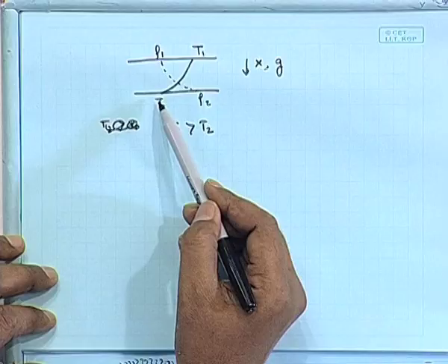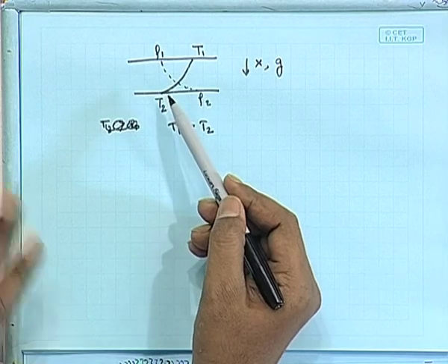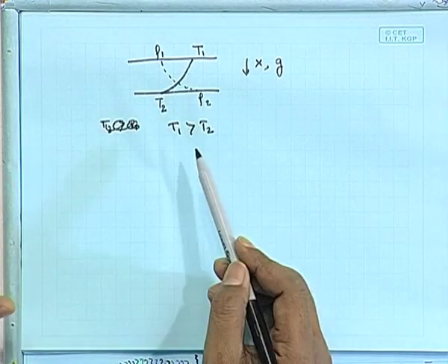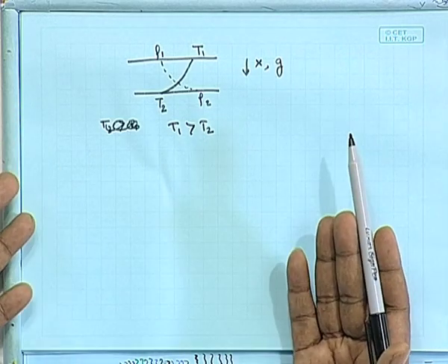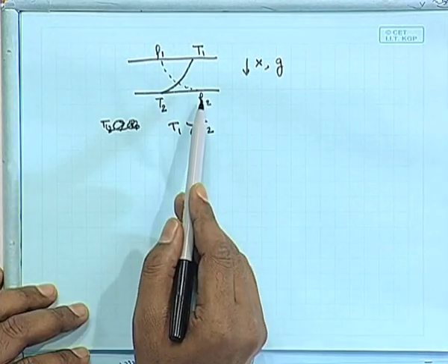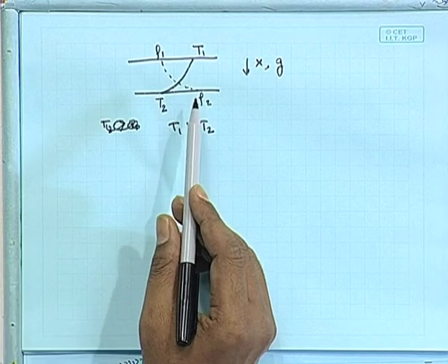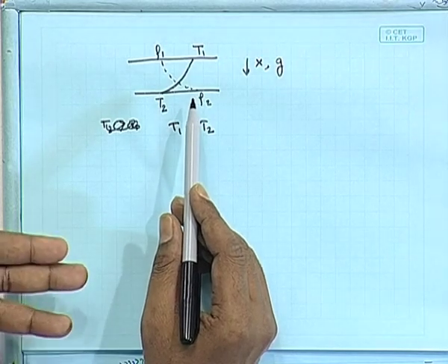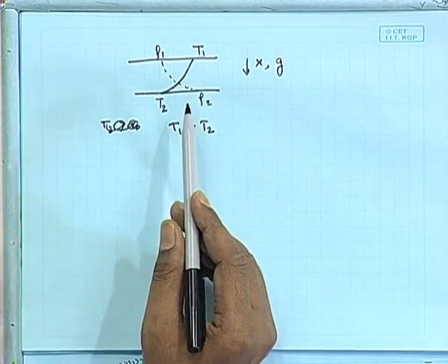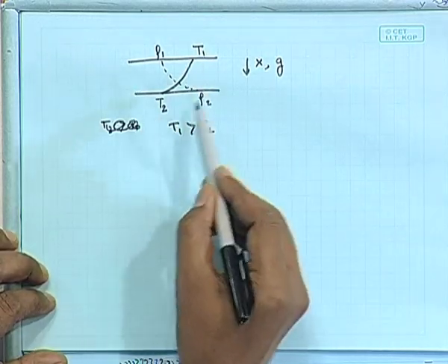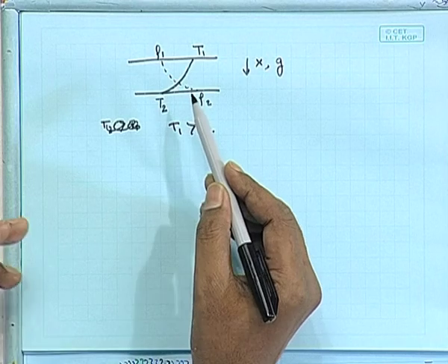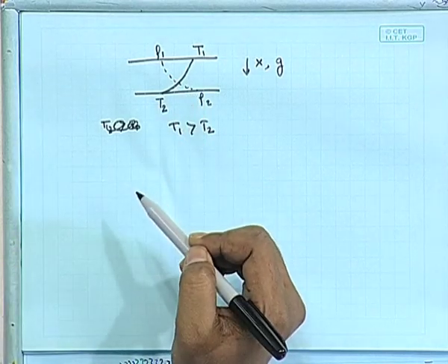The fluid at the bottom plate will become heavier because it is at the lower temperature, so since it is heavier, in the same direction of gravity, it will remain at the bottom plate. So, there is no way to overcome viscous forces, because there is no upward buoyant force acting on them. So, you will not have a physical movement of fluid material.